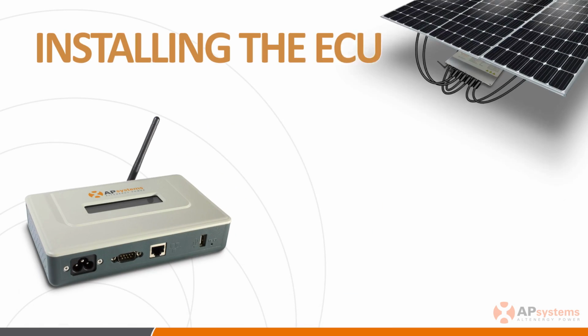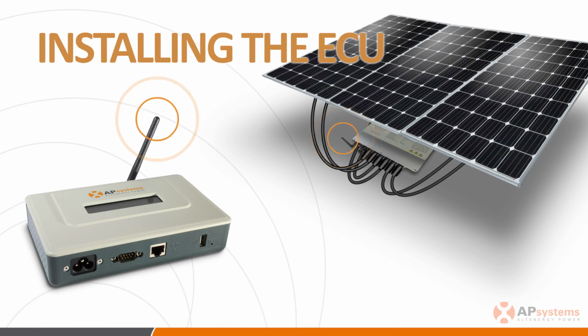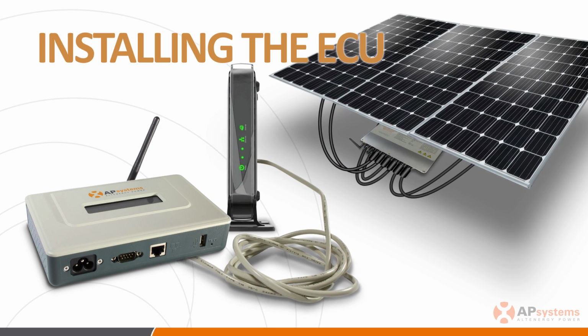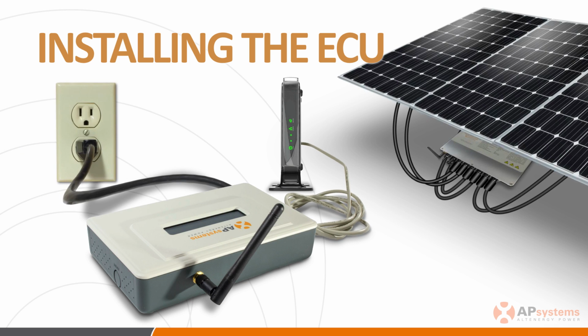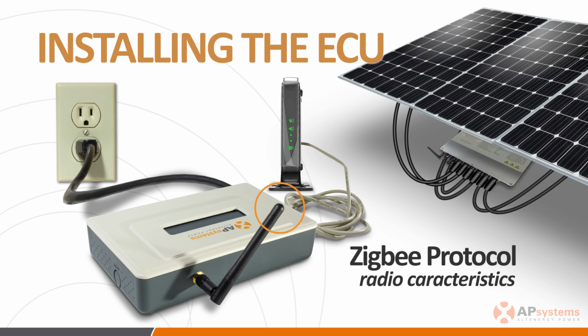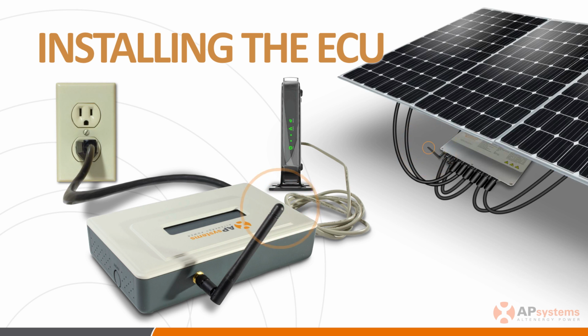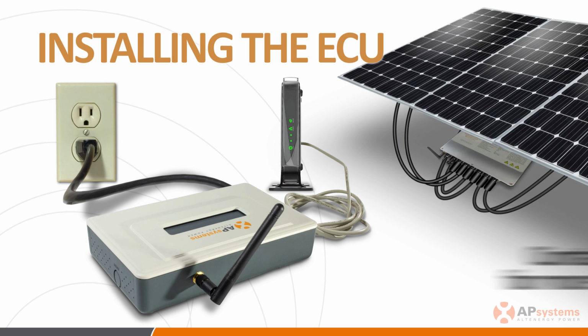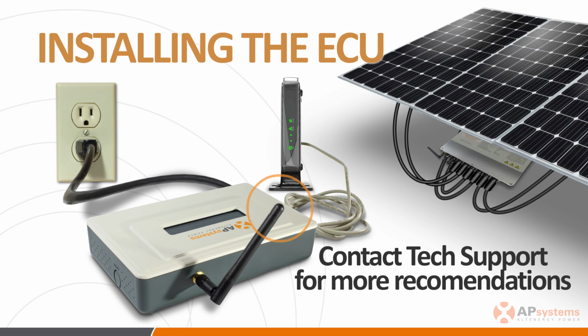When installing the ECU, it's always best to establish Zigbee communication first, and then internet connectivity. As stated earlier in this session, the ECU is plugged into a standard 120-volt outlet, and you want to get it installed as close as possible to the array to eliminate as many communication problems as possible. Because of the radio characteristics of the Zigbee communication protocol, the ECU needs to be within 200 to 300 feet, depending on the site conditions, of the closest inverter in the array. Contact APsystems technical support for additional recommendations if this placement isn't possible.